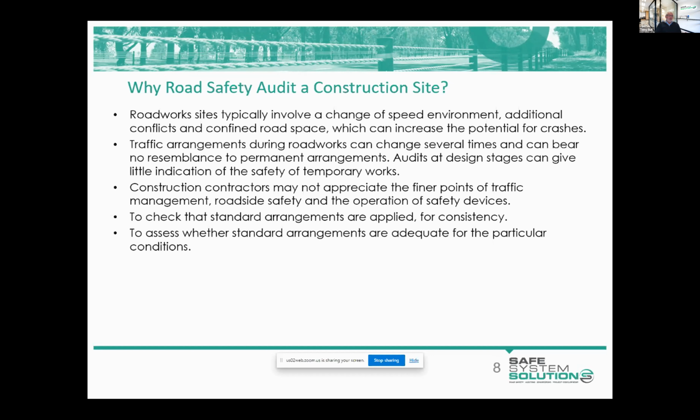We have the water truck out so the dust is being suppressed, and so that the speeds can be managed differently for working hours and outside of working hours. But unfortunately, far too often I come across sites, especially at night time, outside of working hours, that are still signed down to 40 kilometres an hour, yet the pavement conditions are adequate for vehicles to do probably 80 kilometres an hour.